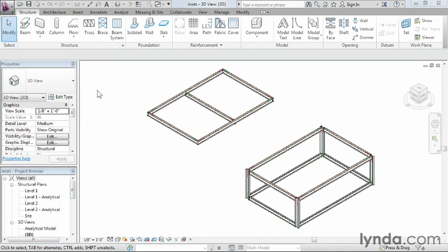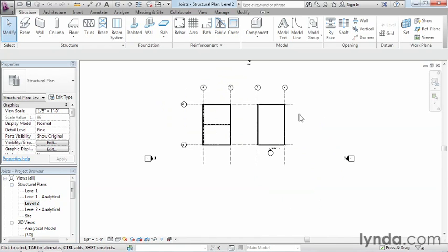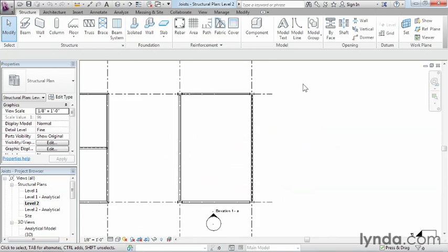The truss tool will put these absolutely massive trusses going across your building with these incredibly strong structural shapes. And it's not really what you want to use. In reality, whenever we're going to be placing a joist in, all it really is a beam. So first thing we're going to do is go ahead and move into our level 2 floor plan. Then we're going to move over here to the right-hand side.